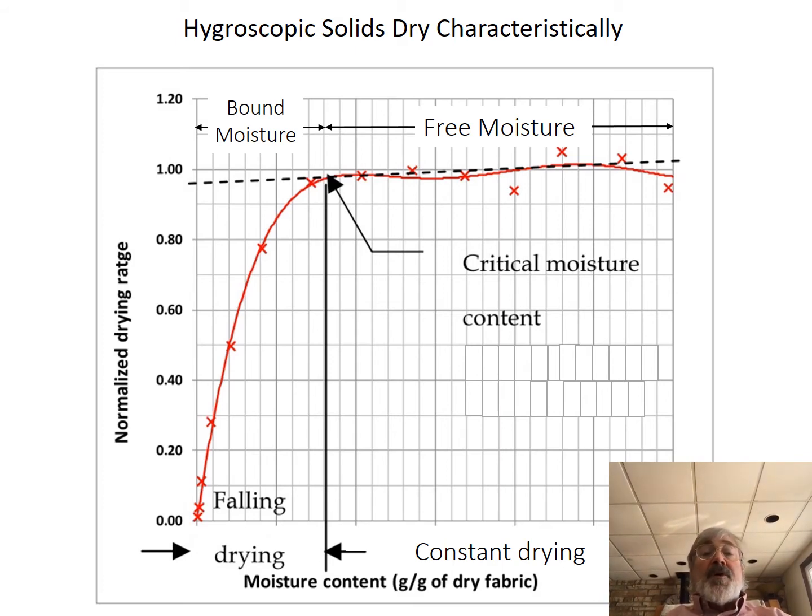If you have exhaust temperature history from a kiln, you can actually draw this right off that exhaust temperature history and use a psychrometric chart. Or on the other hand, if you have this drawn already for your product, then you can build the exhaust temperature history that you're going to see when you turn the kiln on.